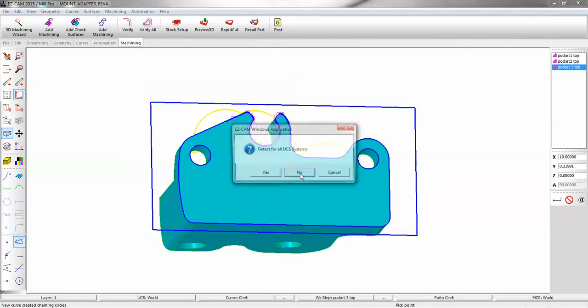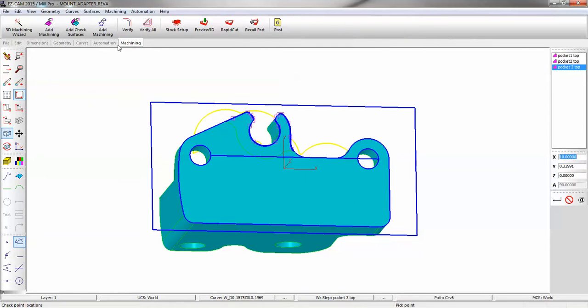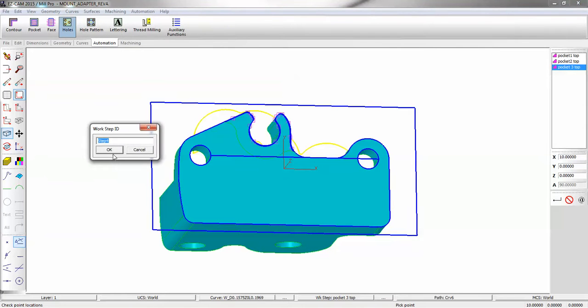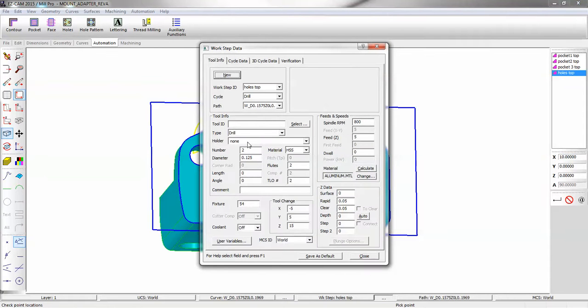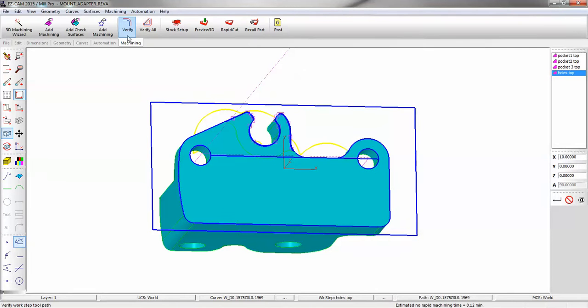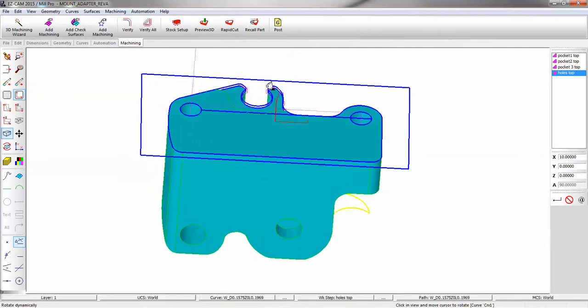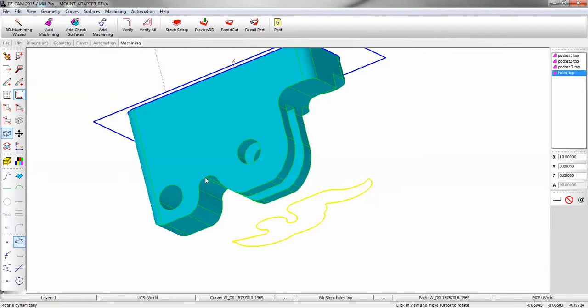We have hole recognition. The diameter of the hole. Hit the auto button, it knows the depth of the hole. I want my drill body to go to that depth, so I'll just add the drill tip angle, hit the auto again. Next we'll cut this side over here.